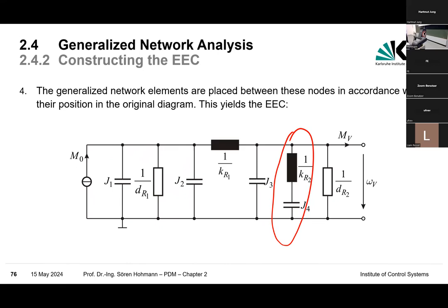So typically, what we have here, for electrical engineers, it's not so surprising. Generally speaking, it's some sort of filter, isn't it? So what the mechanical engineers did is they designed a filter in a mechanical way. And they can damp down, more or less, a specific frequency range, because you have the resonance frequency, you have friction, and you get a spread of frequencies which are damped, and others are not damped.